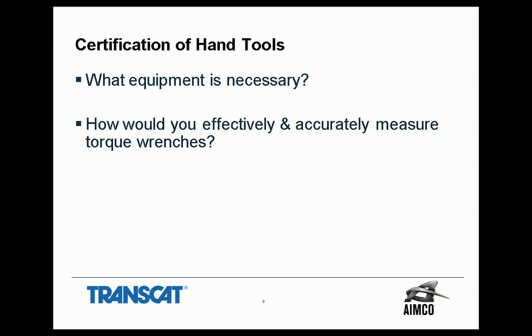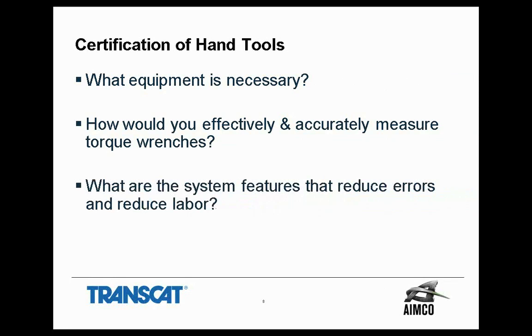So typically, the equipment you want is a transducerized sensor and electronics with a peak circuit, a first peak circuit, a track circuit, and if you're using discontinuous tools like positive clutches, impulse tools, or impacts, you want something that can handle those multiple events in a sample, what they call a pulse mode or a discontinuous mode. It's pretty important to be able to recognize with good resolution the torque point that the device is producing. So fast electronics with multiple measurement modes is typically what people use.